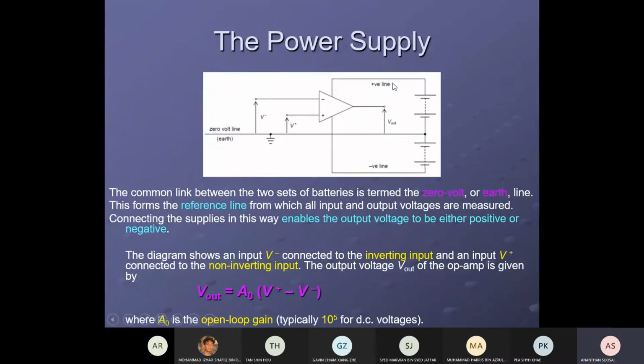Now the circuit is growing. In the circuit, the input will be two voltages. Down here, this is the earth sign. Earth sign means 0 volt. Here 0 volt. You put a battery in between, or you can put a microphone, something which can generate a voltage. These two at the end could be a sensor in the potential divider method to give out input voltage.